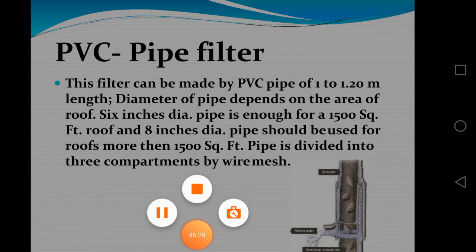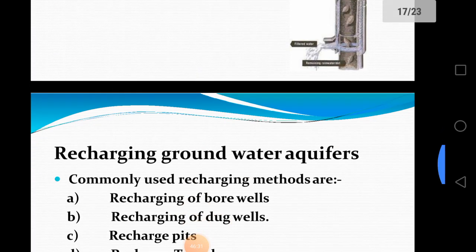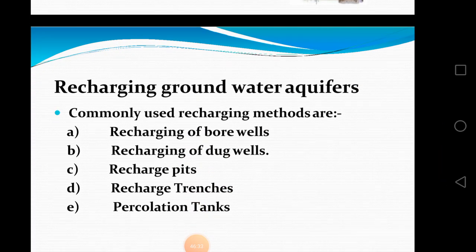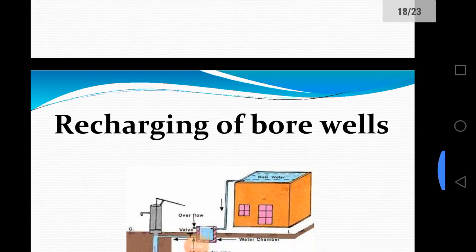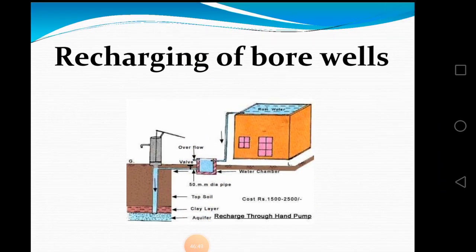Next, recharging groundwater aquifers. How can we recharge the groundwater aquifers? Commonly used recharging methods are recharging of bore wells, recharging of dug wells, recharge pits, recharge trenches, and percolation tanks. We'll go for recharging of bore wells first, because there we just use one small tank when we are collecting the roof water.